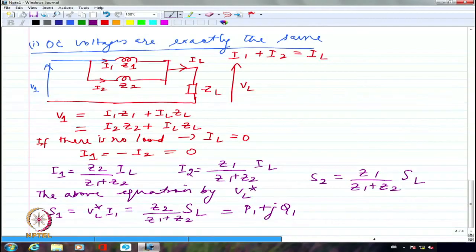Because if I increase it further, say I have put two 1 kVA transformers together because I wanted to supply a 2 kVA load, at 1.5 itself maybe one of the transformers has reached its brim. You can't load it further. So if I try to increase the load further than 1.5 kVA, the transformer which has already taken this 1 kVA will be overloaded in all probability.